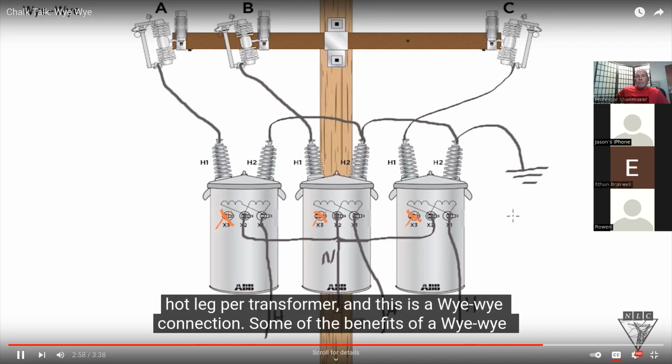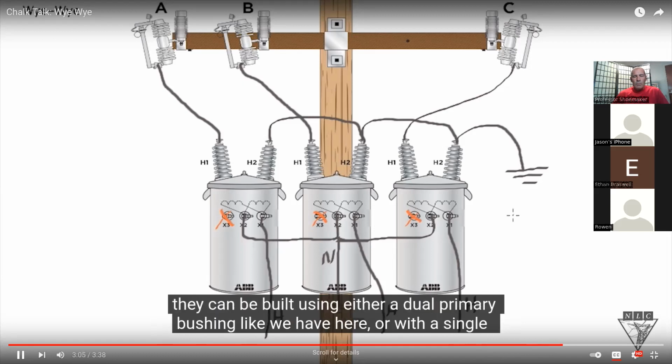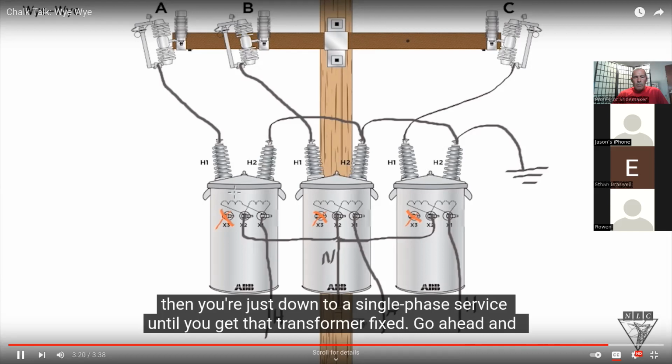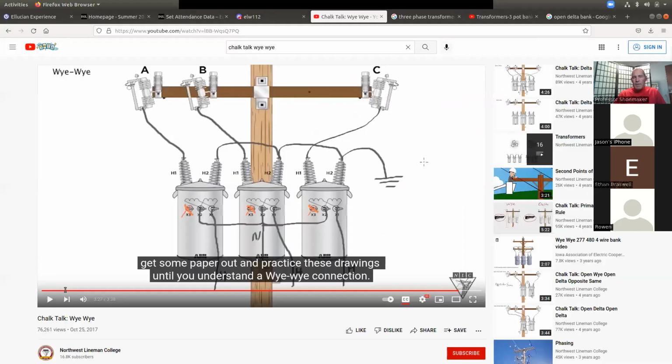Some of the benefits of a YY connection is that all 3 transformers can share the single phase load equally, and they can be built using either a dual primary bushing like we have here, or with a single primary bushing. One of the downsides of a YY connection is if you lose one transformer, then you're down to a single phase service until you get that transformer fixed. Go ahead and get some paper out and practice these drawings until you understand a YY. Yeah, we'll do that later. Okay, so that's all 3 banks that you need to know about.